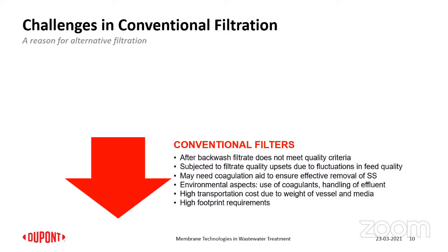There are depth-based filtrations which need coagulation aids, to ensure suspended solids are removed. Like you need coagulation upstream of the filters to ensure that there is better removal efficiency. So this is an additional cost on operation. On environmental aspects, if you are using coagulants, you need to handle the sludge that is being generated through this. It's also a headache, and there is huge cost involved in transporting the vessels. You might see the conventional filters are really robust, and they need heavy equipment investments, and they also take a lot of footprint when they've been installed.